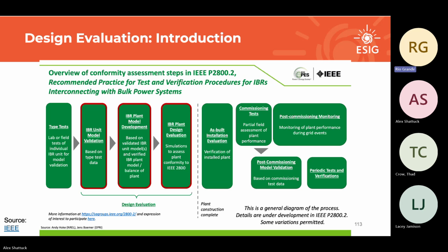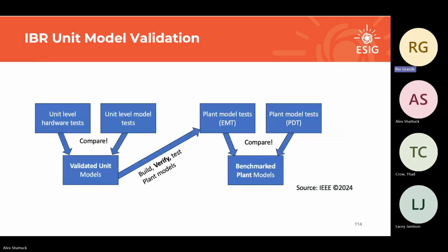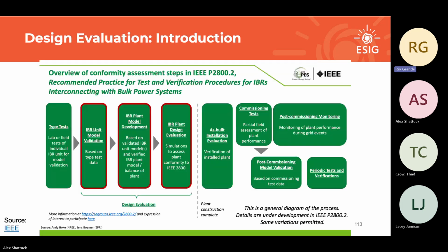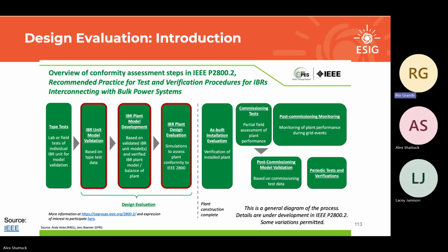The other thing to lead us into, did I do type testing? Yeah, so let me talk about type testing real quick. Type testing is lab or field tests. We talked about it a little bit yesterday. This is basically taking your product, putting it into the lab or in the field, probably the lab, and just cranking it around. You're doing really strong faults. You're doing big phase angle changes, deep faults, long faults, unbalanced faults. Essentially, it's a data person's dream, right? You're doing all of this stuff to get data from the type tests, and then you use that data throughout the process for model validation, checking in, and that kind of stuff.